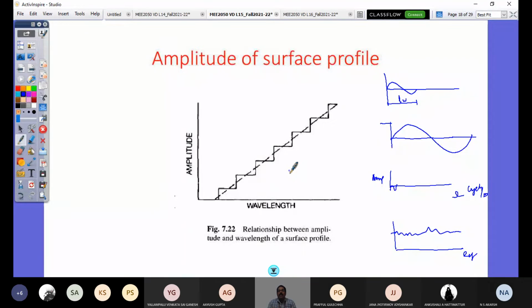You do not have the road in a sequence of wavelength smaller first and then the next, not like that. All are bundled together, and we are not able to distinguish these amplitudes and wavelengths as we measure. Only statistical measures can be helpful, mean and mean square value or autocorrelation function.